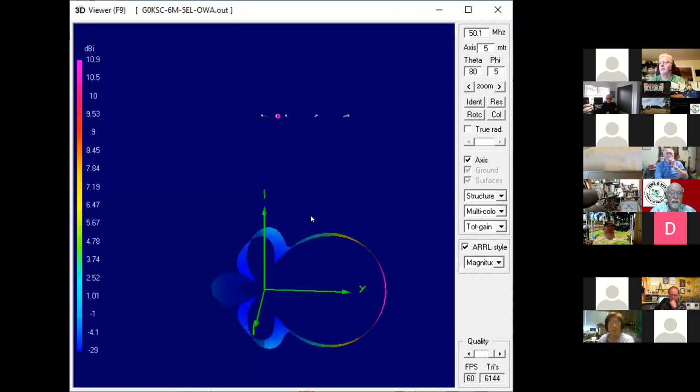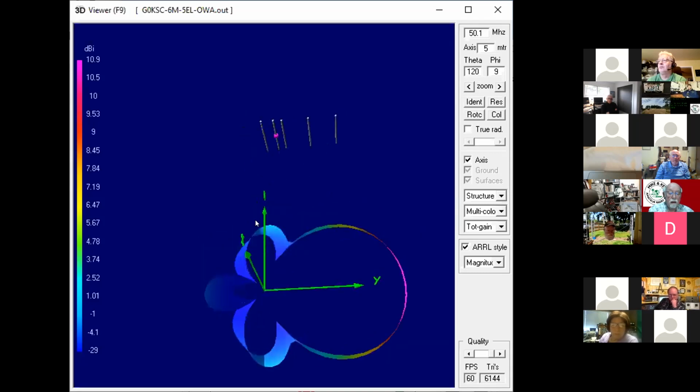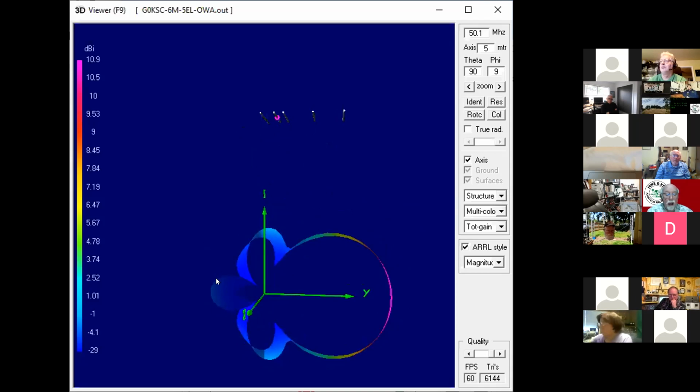Since we did this as a frequency sweep, you're not going to see the full donut. The front to back is from here, the end node, to the front node. And whatever that delta is, that's the front to back. Front to rear is looking at these nodes. I'm not sure I can get this any better for that. So there are two numbers you care about: front to rear, front to back ratio. And that's what it looks like. So those big little side lobes really cut down on the gain of the antenna and also introduce the noise source, the noise ability to pick up the noise.